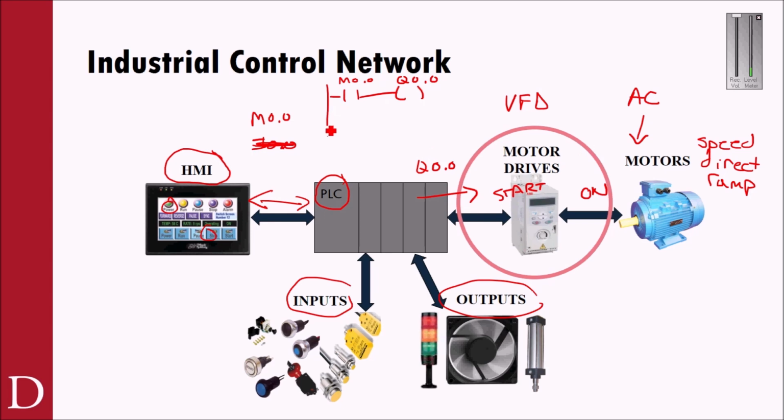Okay, and maybe I've got another bit, an M0.1, that I want to use to reverse my motor. And M0.1 from the HMI goes over to Q0.1. And Q0.1 then is wired up to the reverse. And now all of a sudden I go in the reverse direction.